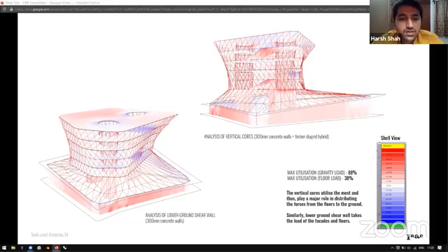And it was good to know that the floor load doesn't affect the cores as much as the gravity load. And the shear wall aids majorly in relieving the stress from the cores. The results therefore showed that overall the shell elements work less effectively in load transfer compared to the beam elements.